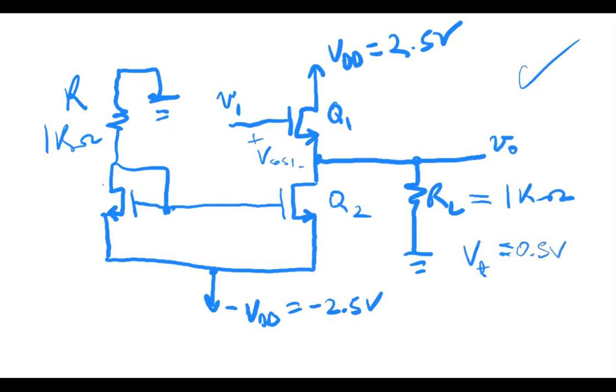And the mu, in this case, sorry, they're all N channels, so it would be the mobility of electrons, the capacitance of the oxide at the gate, and then the width to length ratio of the channel. That is 20 milliamps. So this is essentially the transconductance of the transistors.